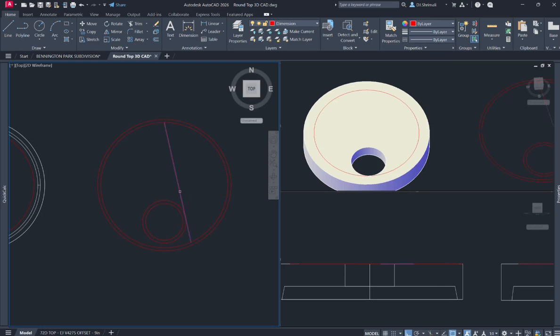You cannot see it in this video, but what I did is I snapped at the middle of the circle or the edge of the circle, and then I pressed shift plus right click of the mouse and selected tangent, and you will see the tangent snap, and using that I created those two tangent lines from the circle, outside the circle. And now I'm offsetting it 6 inches using the offset command. As we go you will see that.